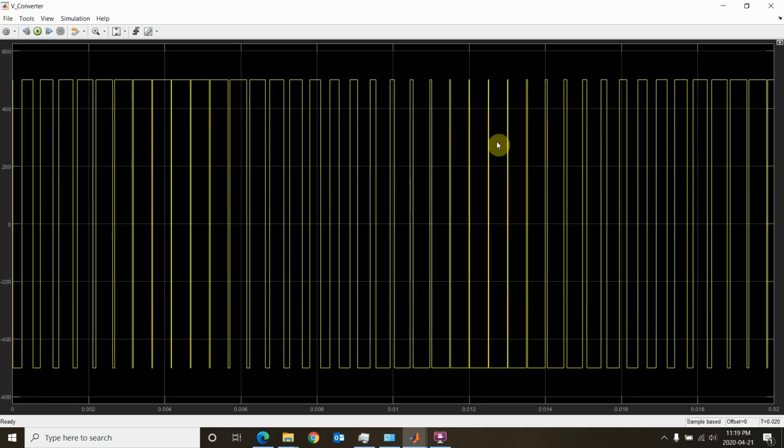Okay, so now this looks much better, right? So I can actually see that this is similar to a sine wave, right? So this is how we model a sine wave using PWM signal. You see here the width of the pulse is basically increasing up to here and then decreasing, and then it goes to negative part, increasing, decreasing, and then it continues, right? If you find the frequency of this one, it should be again 60 hertz. So after 60 hertz, it repeats itself.